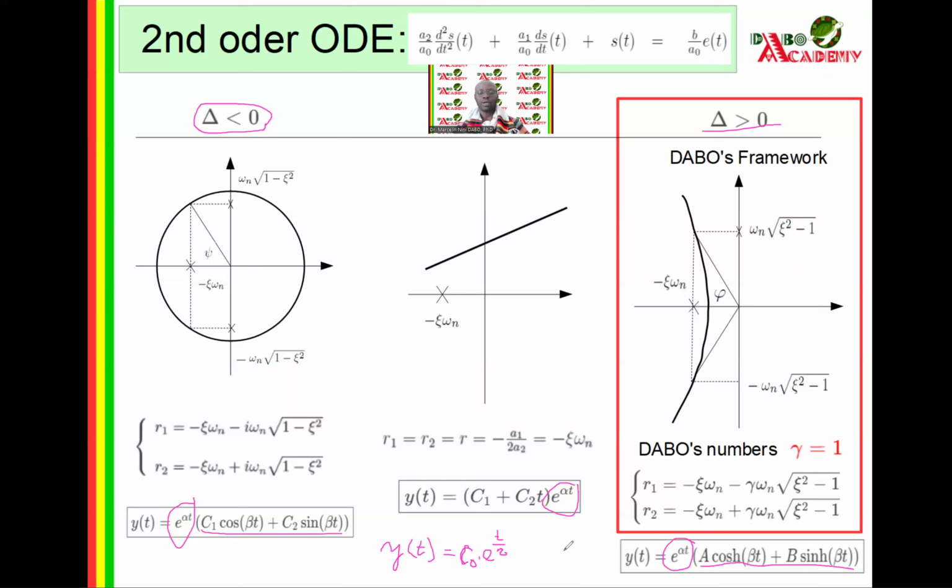So if you look at this expression, you can see that this is a constant, C0, times an exponential. And here you have an exponential, here you have an exponential, and here you have an exponential. This is why, thanks to this contemplation of these results, I have introduced that for second order dynamical systems, in reality, there exists only one single time constant. That is a double of what I have defined and called a relative time constant of my second order dynamical systems.